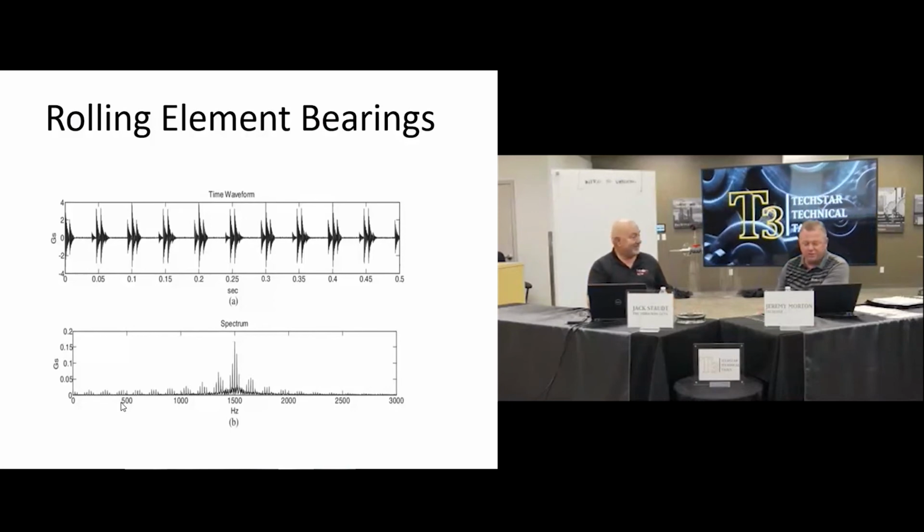So for stage 1 and stage 2, do you have an estimate, or is it such a small defect at that point that you just keep monitoring it? It could be 1 month or it could be 1 year. It's all based off the RPM. You could have one that you identified 9 months before, and it's turning 900 RPM. Or if you have one turning 3,600, you may not get but 30 days out.